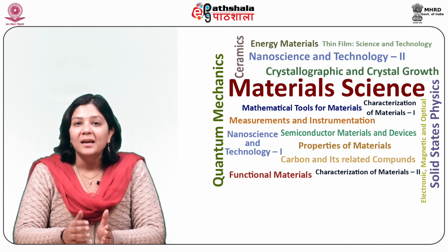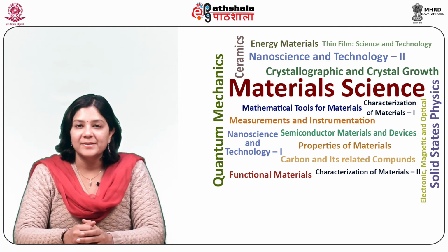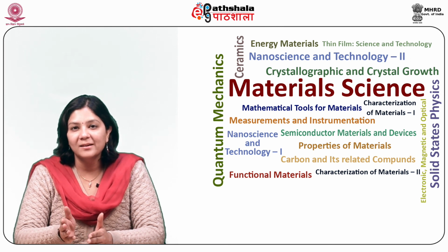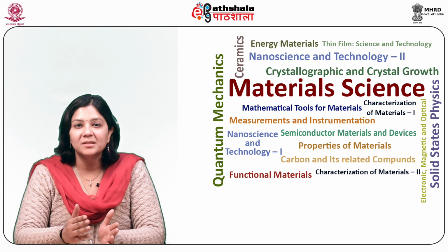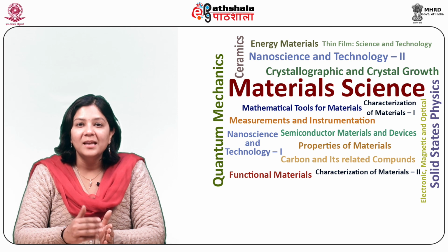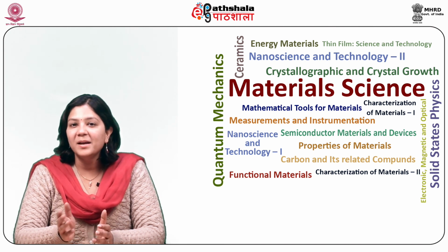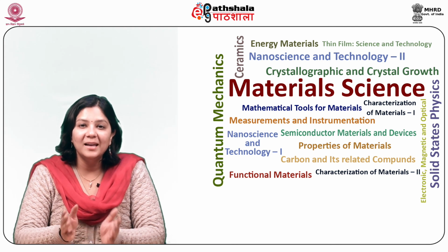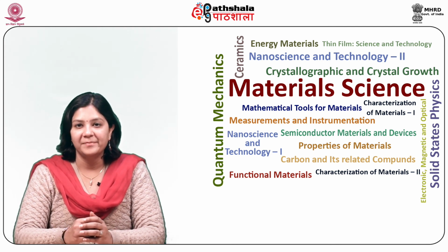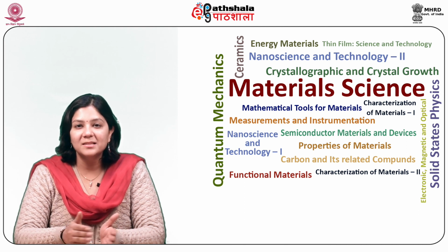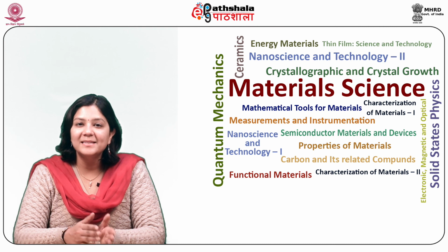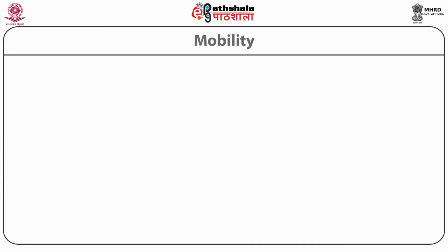Inelastic scattering. Inelastic scattering causes a significant amount of energy exchange. Like elastic phonon scattering, atomic vibrations cause energy band deformation. Optical phonons that cause inelastic scattering have energies between 30 to 50 milli-electron-volt, while the typical energies of acoustic phonons are less than 1 milli-electron-volt. The carriers undergo considerable variations in energy during the scattering process.